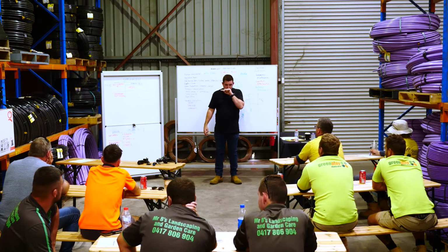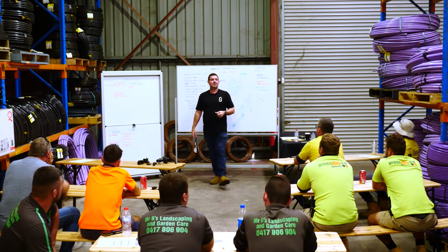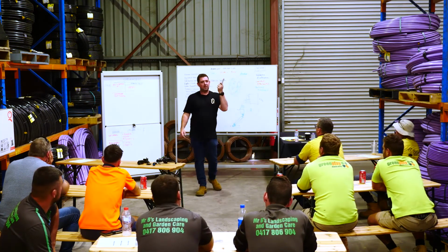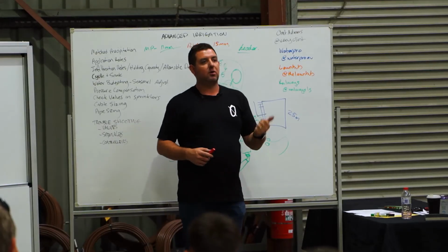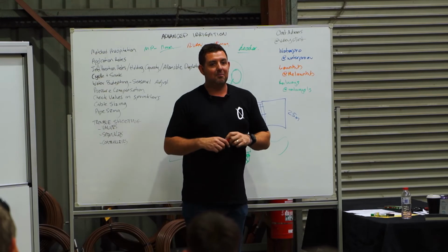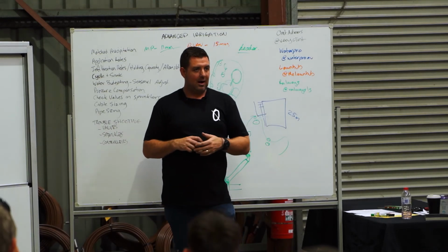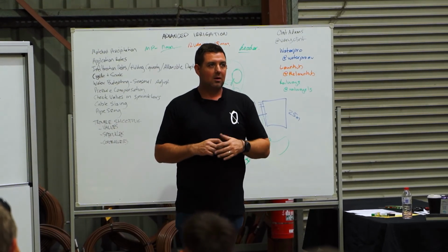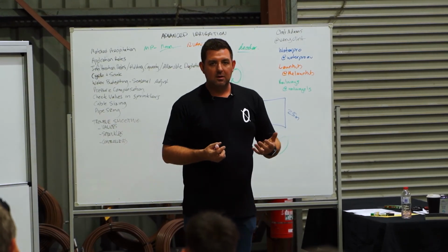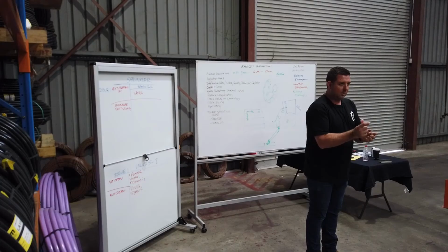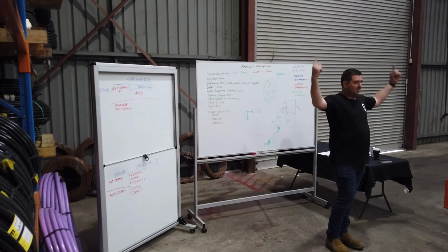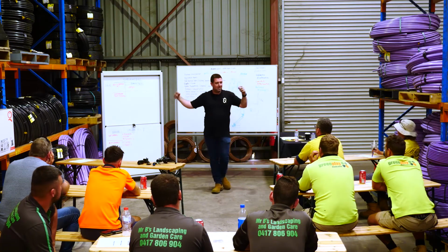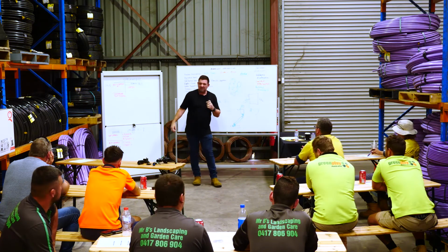The funny one we've had is my sprinklers are just spraying straight in the air. Generally that's because they haven't replaced the flushing nozzles with sprinkler heads. Obviously it's unlikely to happen at trade level, but retail clients, if they're not explained clearly that the MP rotator has to be actually fitted to the body and you take the flushing nozzle off, they've just got these kind of geysers everywhere. So that's probably it with sprinklers.